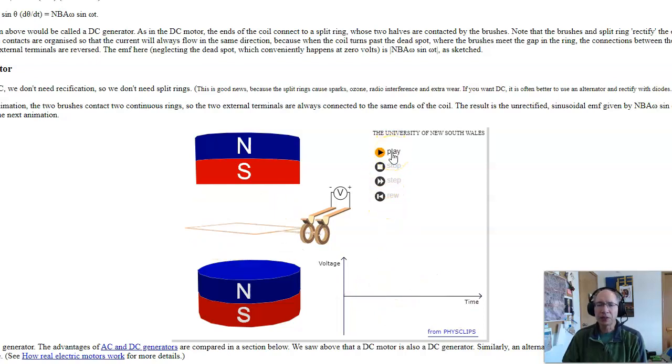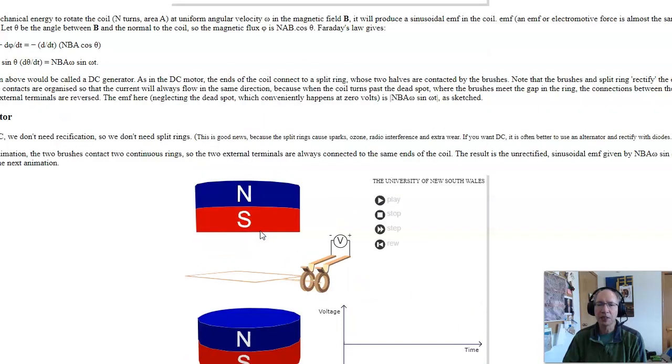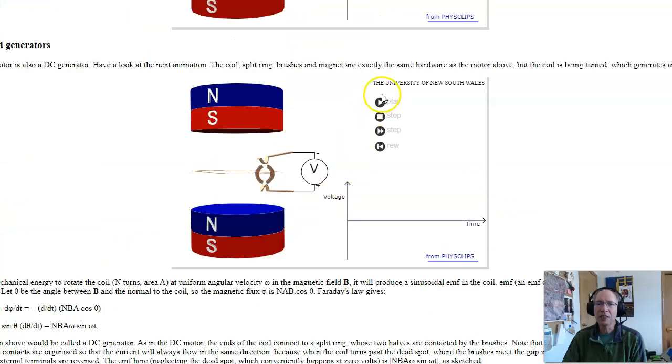Motors and generators are the same thing. So this is also an AC motor. Apply an AC voltage to the rotor and it'll spin. That's a single-phase AC motor. A DC motor looks like this. You add a commutator. What the commutator does is at the zero crossing, I flip the leads. So the net result is as I spin it, I get a DC voltage. Motors and generators are the same thing. If I do the same thing, apply DC voltage to the motor, it'll spin.